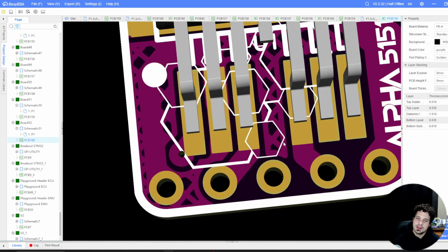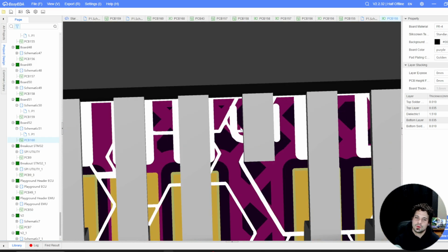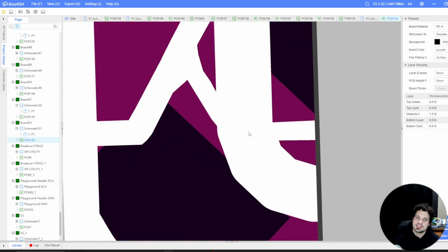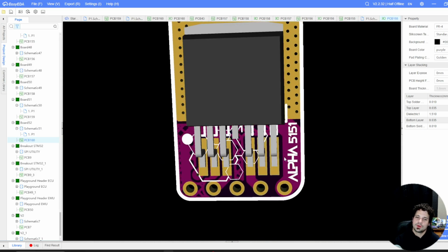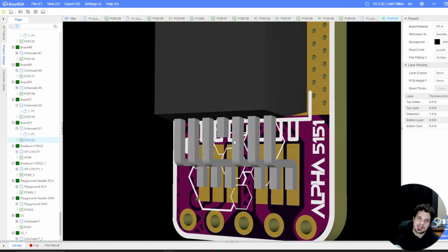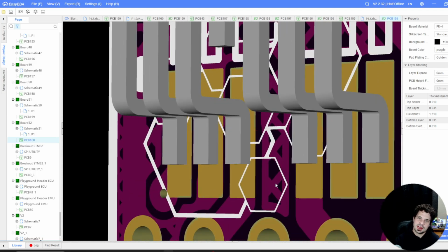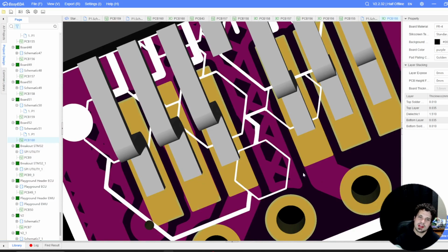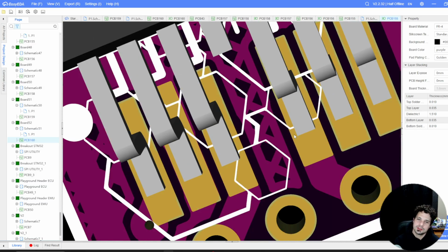And as you can see, we're actually utilizing really large traces throughout our design. You may be questioning what these little 45-degree angles are, and this is actually a plane feel that I do to prevent ground noise and other things like EMI from affecting the board. So something you'll notice that's typical amongst Alpha boards is I have this little grounding layer in here that has a pattern to it, a 45-degree crosshatch, sometimes greater, but that's kind of a trademark of something that I do, and it is in all my boards.